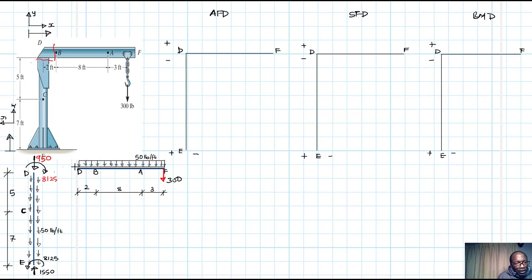We expect also here a shear force, let's call it V. If you apply summation of forces in the y direction, you have V, and an equivalent force that we had calculated, which is 50 by 13, which is equal to 650.